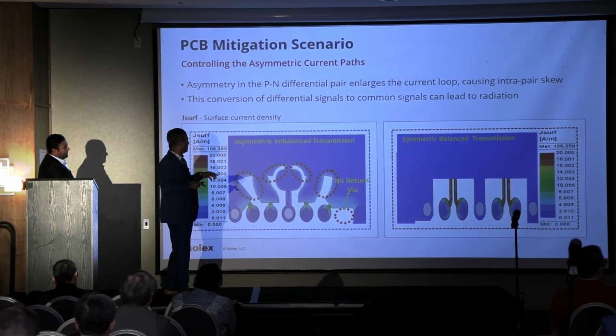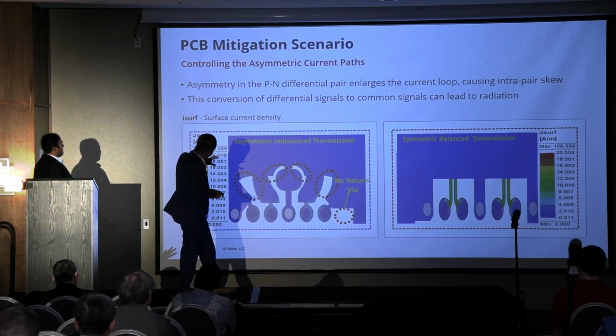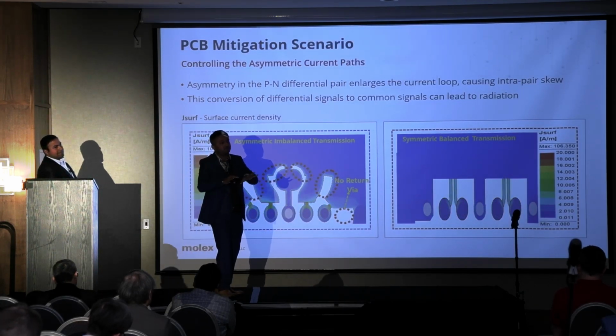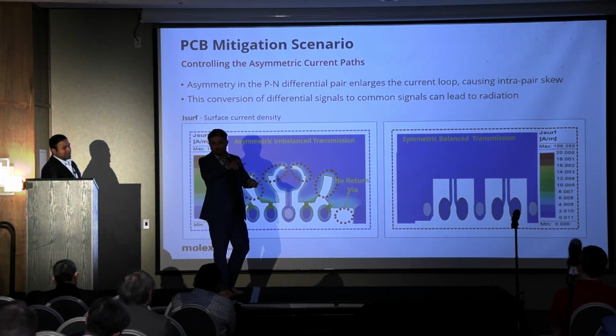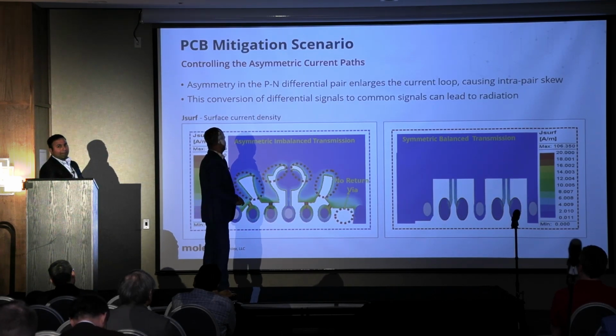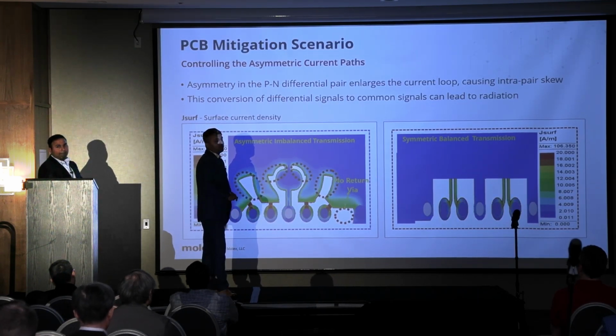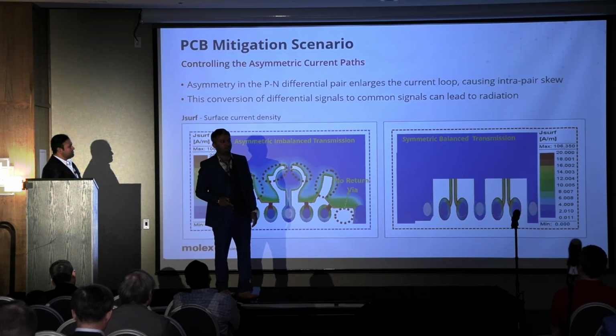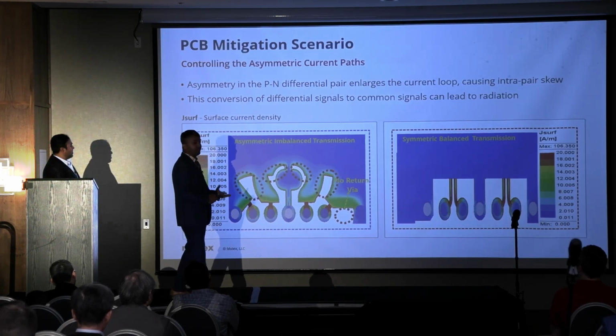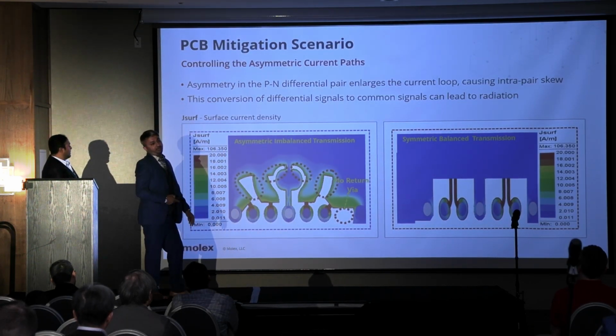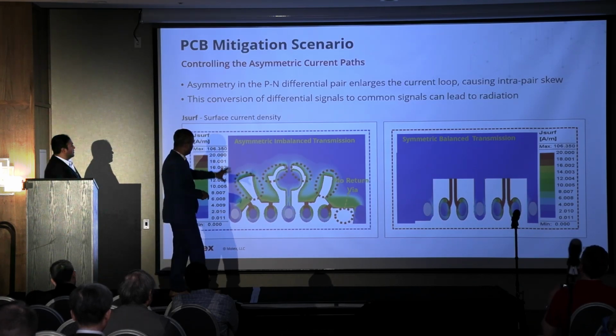So the displacement current starts searching for the least impedance path, and in that process you will see current get distributed across the plane, and the overall loop will be more. And that is a major problem for mode conversion. Or in other sense, it might create unwanted or accidental radiators in this kind of scenario.